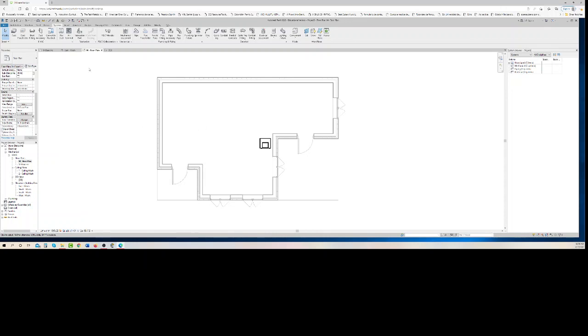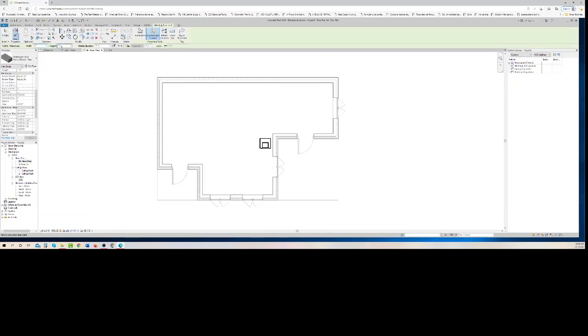So our next thing to do is to put in the main duct, and we're not going to do any design. We're just going to leave it how it is, but we're going to put in rectangular ducts, mitered elbows, and taps.